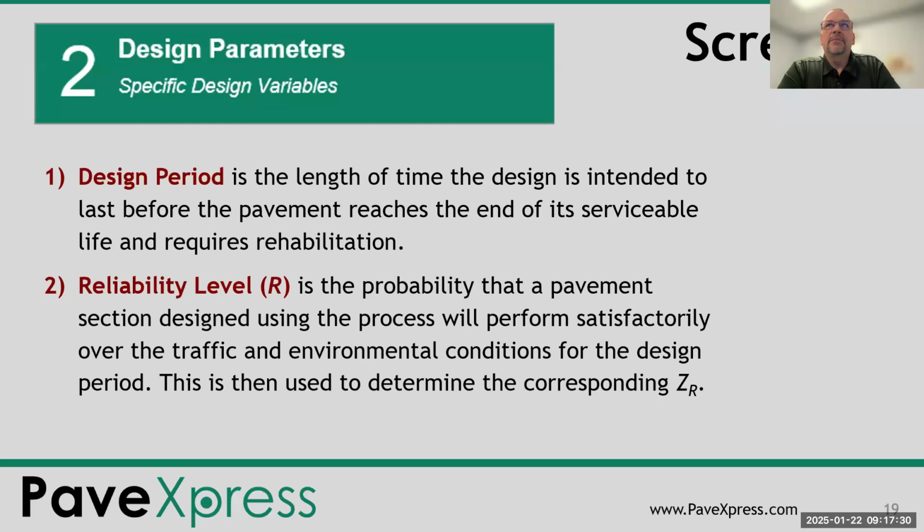But really, the serviceability was set up during the road test, and it is similar because it was basically people's feelings about how the roadway looked and rode, and where they thought the terminal serviceability was. And depending on your roadway classification, your terminal serviceability may be a little higher. Maybe it's 3, and on some other lower volume roads and things like that, maybe it's a 2.